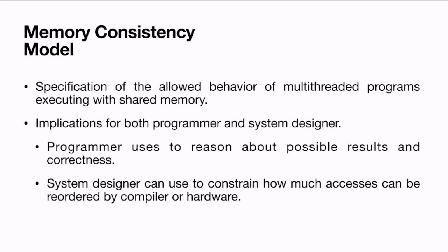Similarly, if the memory consistency model says you should not use any store buffer, because it is going to give extra possible outcomes that should not be allowed, then the hardware system designer is going to disable all the store buffers, or he may disable out of order execution or whatever. So this is basically a reference point for both the programmers and the system designer, who look at it and then accordingly work.